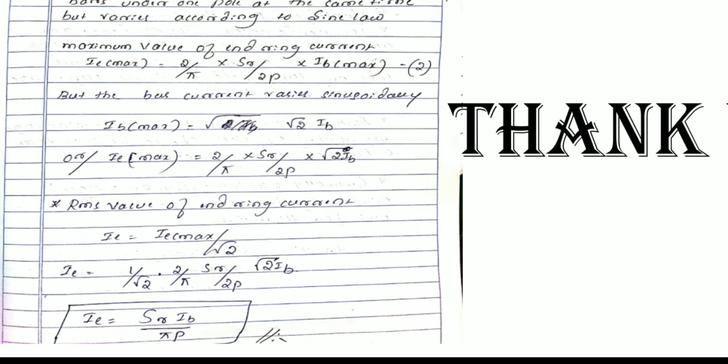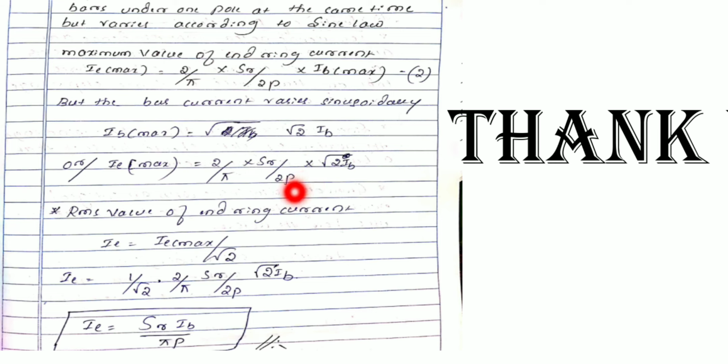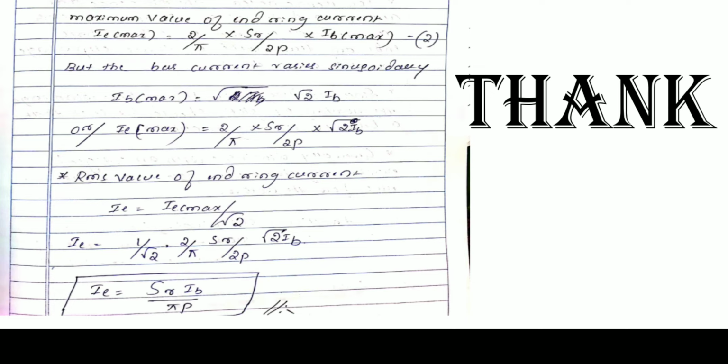Next, when we take the RMS value of the end ring current, RMS value means the maximum value of the current divided by root 2. So IE will be equal to IE max divided by root 2. IE max is what we got here: 2 divided by pi into SR divided by 2P into root 2 IB, divided by root 2, that is 1 divided by root 2 into IE max. This I substituted here. From this equation we can write it now.